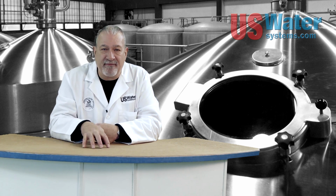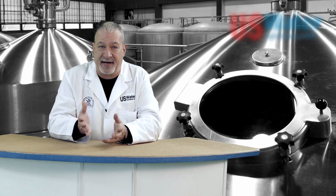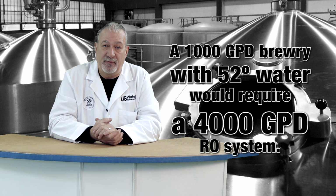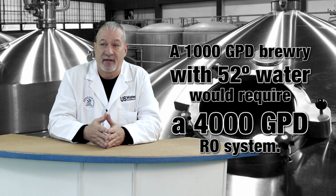It produces 1,000 gallons a day if it runs 24/7. It has to run all the time to produce 1,000 gallons. That's not good. That's kind of like running your car at 120 miles an hour all the time. My idea would be if you needed 1,000 gallons a day, you may want to go with a 4,000 gallon a day system, which with your 52 degree water would really be about a 2,000 gallon a day, meaning that it would have to run about 12 hours to fill up the tank.